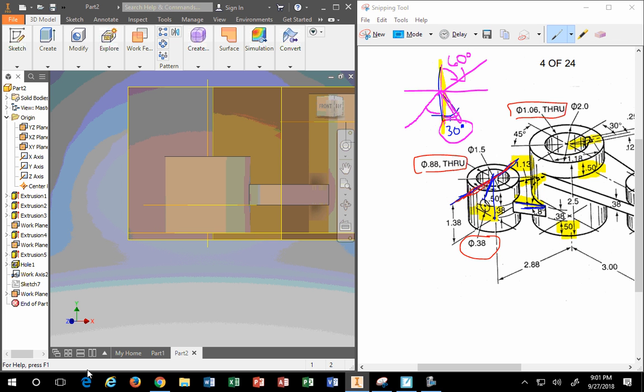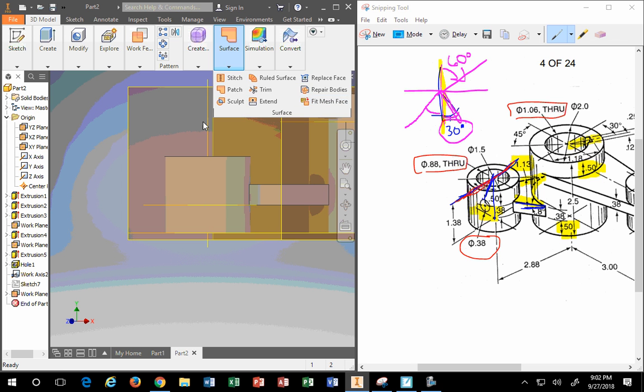Where's my machinist? It's in a particular kind of vise, right? So that the part doesn't turn, doesn't rotate on you. What's another way? What do you put in the center of it? You put a little mark? What's it called? Yeah. Right. So what you do is you basically tap it, you touch it, so it makes a little point. So when the drill goes in, it sits into that point, so it drills in that spot. So what we need to do is our equivalent of that on this round body, using this new plane.